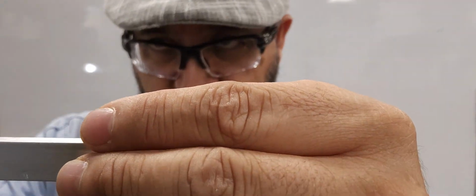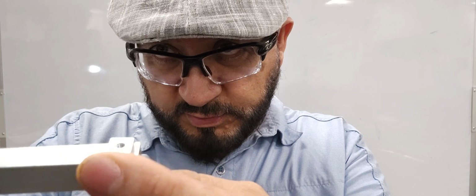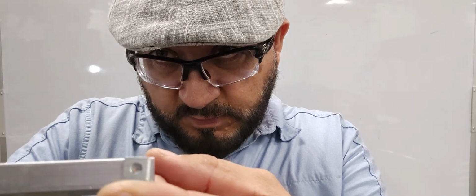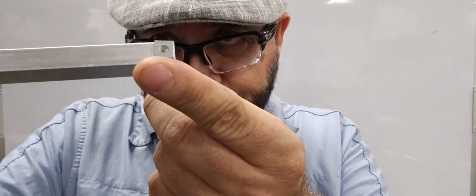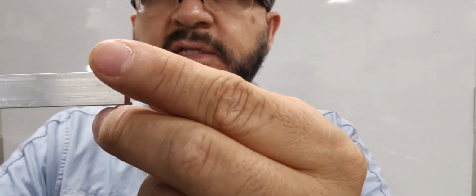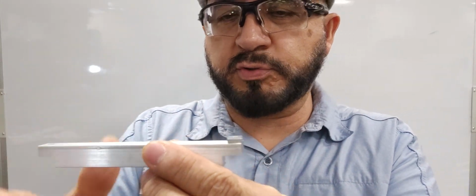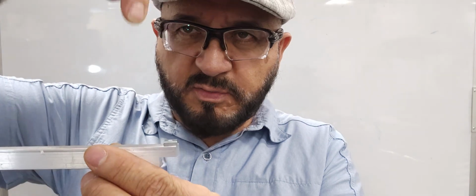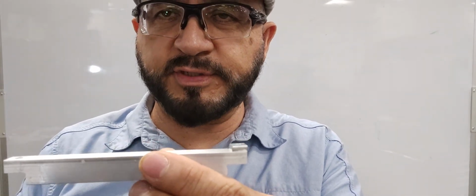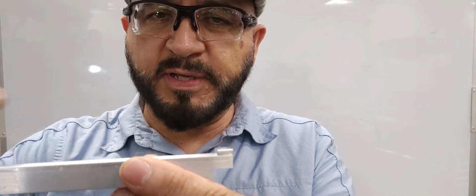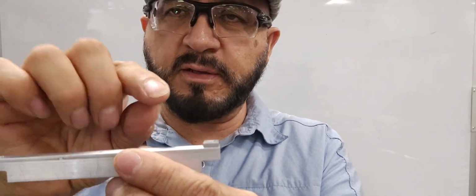right there. You guys can see it's going to be a challenge because I'm going to turn this so you can see it. Very little space in between, about 50 thousandths, to create a pocket in there. But the problem is that most tools that cut into the material, they're round. We need to make a square pocket. So I'm going to have to be using 3 different tools to do this. I'll show you that in a little bit, but first let's define what the dimensions are.